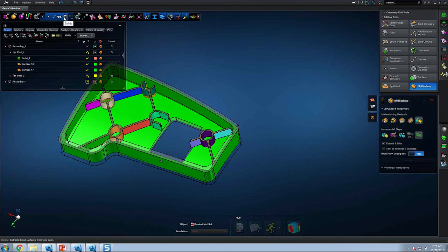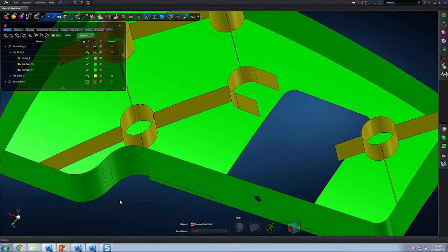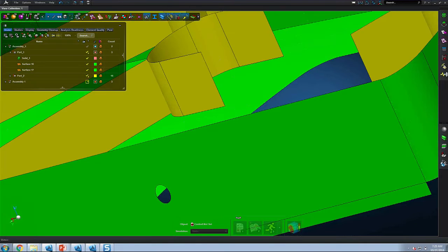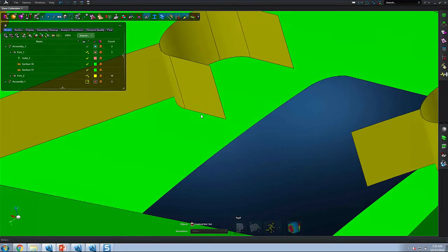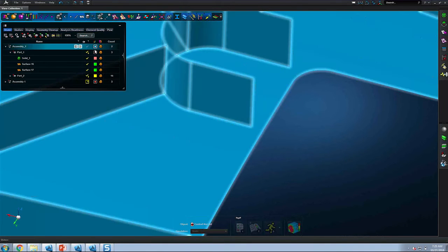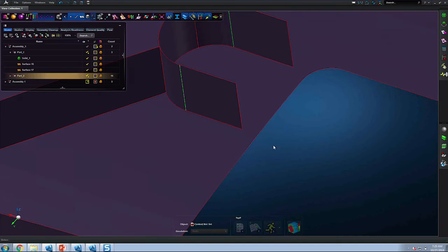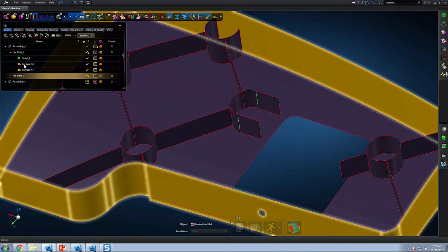Now, of course, our work here is not complete. This brought us up to 80% completion of this model. Now what we have to do is fix a lot of the gaps that you see here on the screen. There's a gap between here and here. Maybe it might be worth showing the free edges in this model. So here in red, you find all the free edges. I'm going to make this purple just so it's a little clearer when you see it on the desktop. So we have free edges here that we can remedy, and I think I'll do that right now.